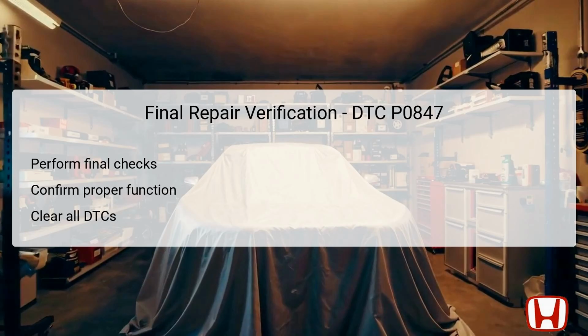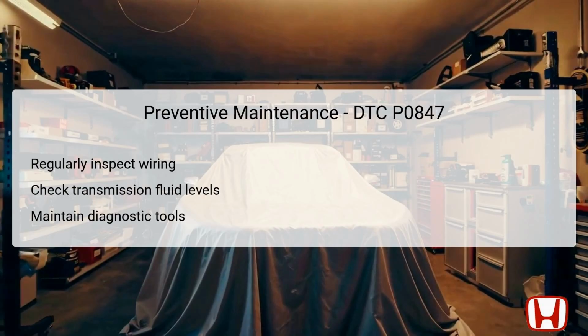This comprehensive approach ensures the issue is adequately addressed, and reaffirms the reliability of the repairs made. As part of preventive maintenance to mitigate DTC P0847 from reoccurring, regularly inspect the wiring associated with the transmission fluid pressure switch and related circuits.